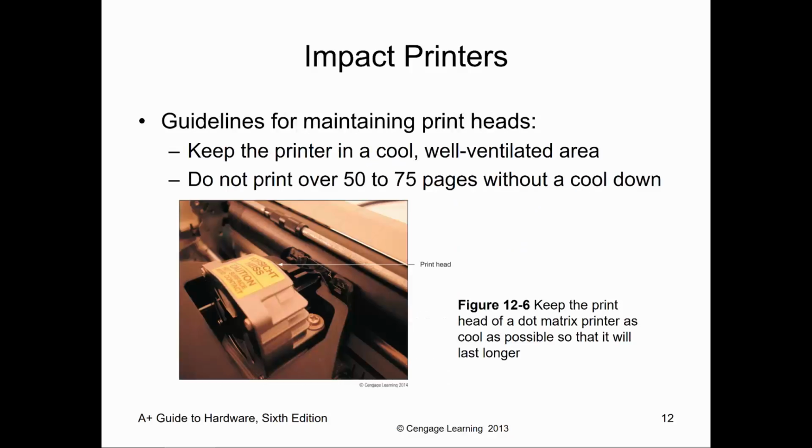Guides for maintaining the print head is basically keep them in a cool environment, well vented. Don't do several pages at a time. You have to be able to let the device cool down. 50 to 75 pages, again, very subjective. Normally, you print a little bit, you let it cool down, you print a little bit, you let it cool down. How much you print really depends on your printer and your environment.